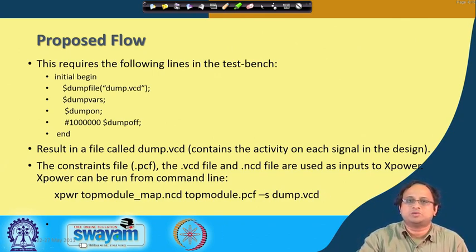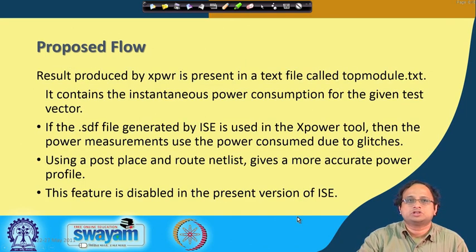This can be, I would say, the in-house arrangement of doing power analysis, where you do not have access to sophisticated tools. Even if you have access to sophisticated tools, from here you can try to understand what the points of interest of your circuit are, and you can focus on your real power trace at those points.